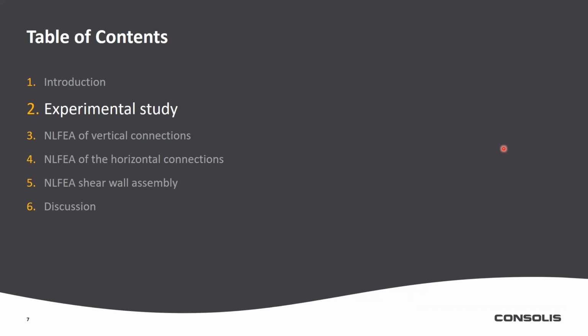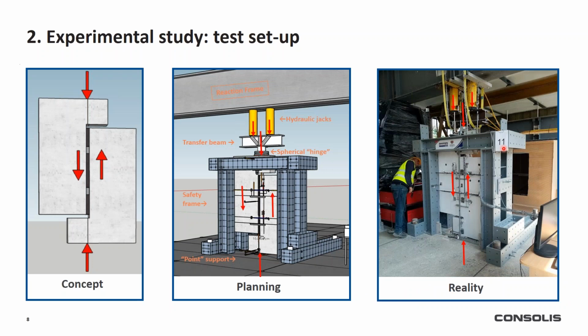And I will start with presenting the experimental study. We relied on the push-off test concept. This is a concept widely used for testing reinforced concrete and precast connections subjected to pure shear. We can see here the planning of the test setup in the laboratory.